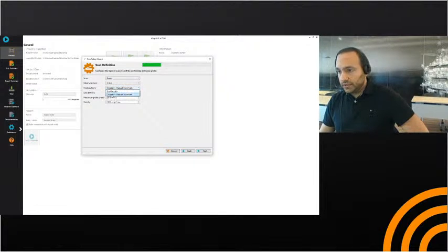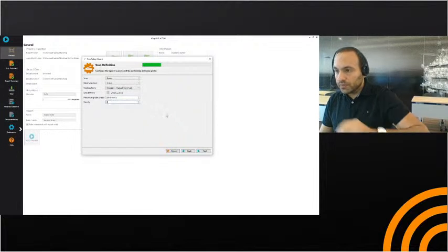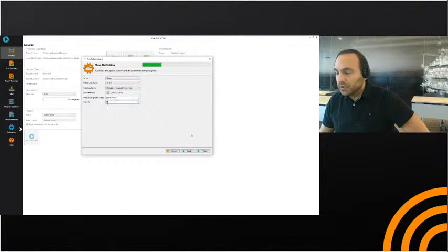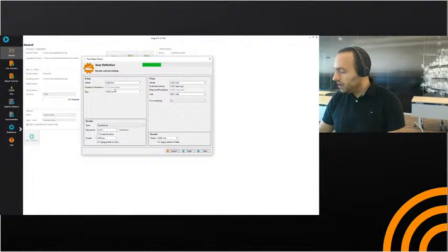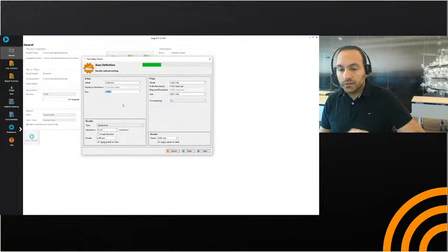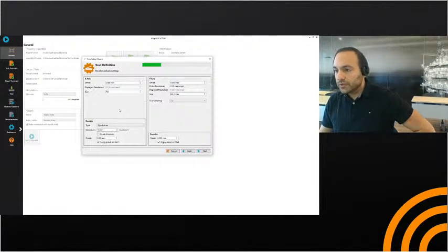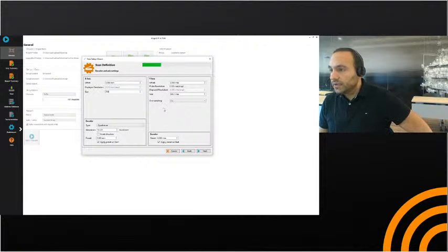Here I'm selecting the encoders. So this is the encoder of the scanner and a manual incrementation. Let me put 4 samples per millimeter. This is the resolution you want to put in the scan direction. So here is my scan definition. I know that I have a 55 centimeter length pipe, so let me put 700 to have a longer C-scan.